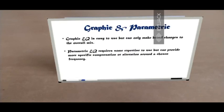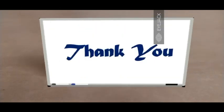Alright, we have seen graphic and parametric EQ. What we can conclude about them is that graphic EQ is easy to use, but can only make broad changes to the overall mix. It is not as flexible to use as a parametric EQ, whereas the parametric EQ, on the other hand, requires some expertise to use, but can provide specific compensation or alteration around a chosen frequency. They can be used to perform surgical level work, which is often the case in professional audio editing or audio mixing.